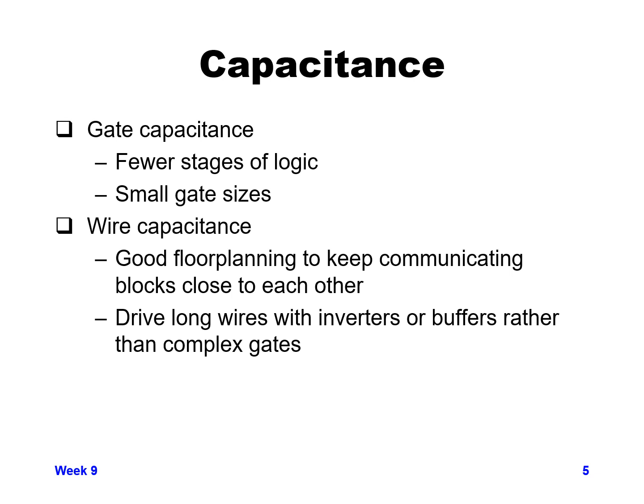As an example, a lot of times with an auto place and route or some sort of automation tool to create your logic, it can throw in extra buffers just because it says, I don't really need to make this logic fast, and there are places where it doesn't optimize for power. It might be optimizing for other things, and throw in extra stages and potentially extra gate capacitance. So being able to take out logic that isn't needed